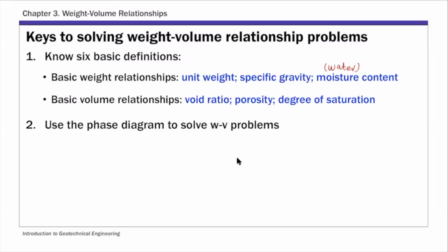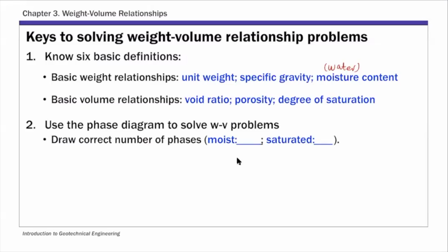And then when it comes to actually solving weight-volume relationship problems, that phase diagram, that block diagram I introduced, is an important, very useful tool. So you need to learn how to use the phase diagram to solve weight-volume relationship. And again, the best way to learn this is actually through examples. I'll go over quite a few examples in this chapter using phase diagram to solve weight-volume relationship problems.